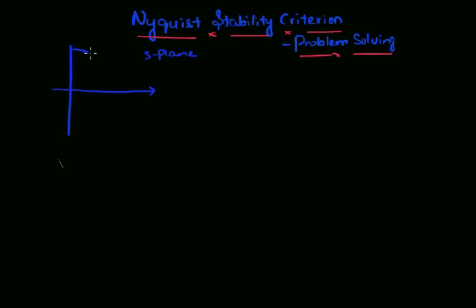Okay, in Nyquist stability criterion, we take a Nyquist contour in which we take the radius of this semicircle to be r, and we assume r is tending to infinity, and we take the directions in clockwise direction so that the enclosed area is in between these lines, from Cauchy's principle of argument. Okay, now this is called Nyquist contour.